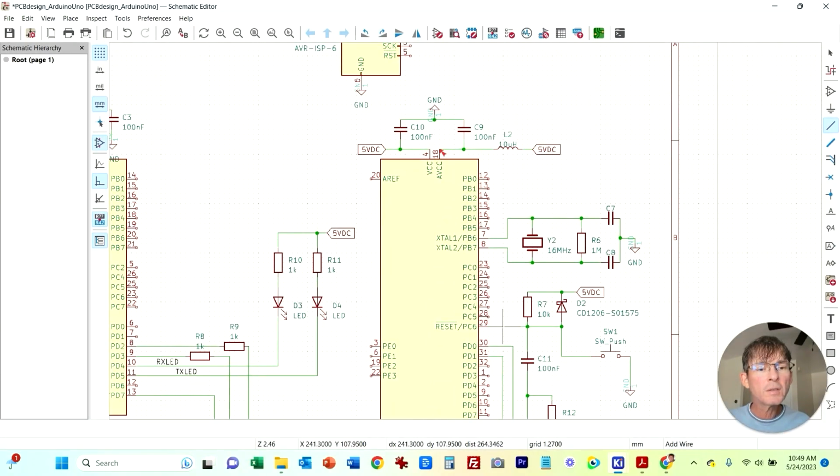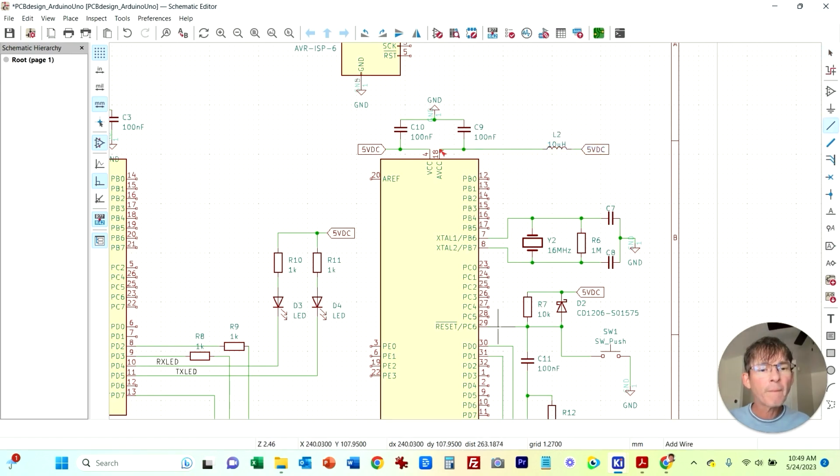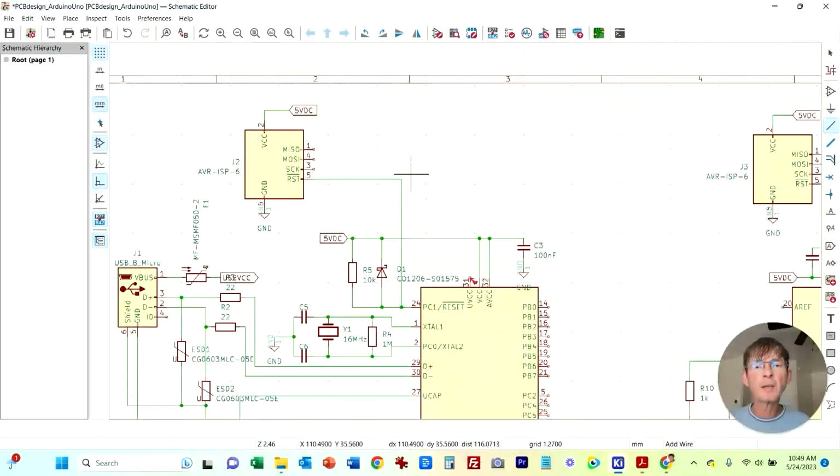We'll just tap right here off the reset, and let's take that there and just move over a bit. Whoops. See, you have to be careful there. That disconnected it. That's not what I intended to do. So I'm going to try this again. Let me just clear this. All right, there we go. Okay, so those are both reset lines.